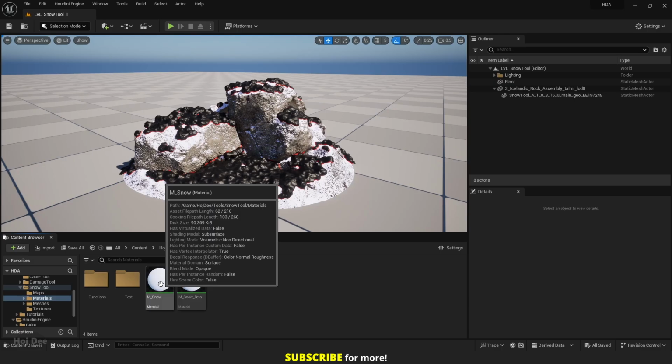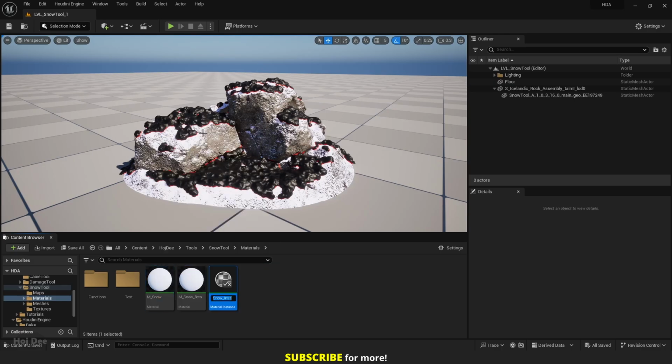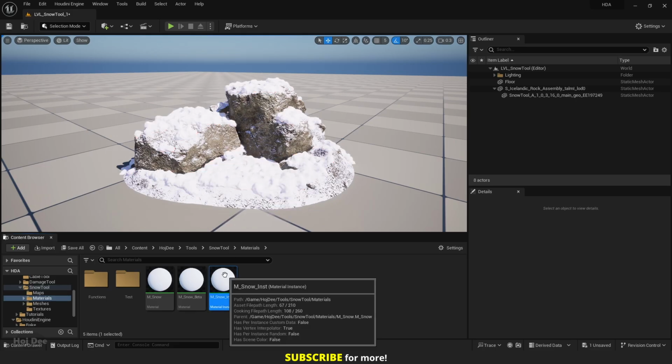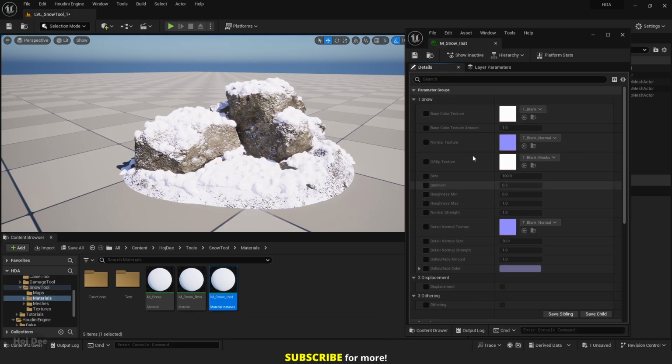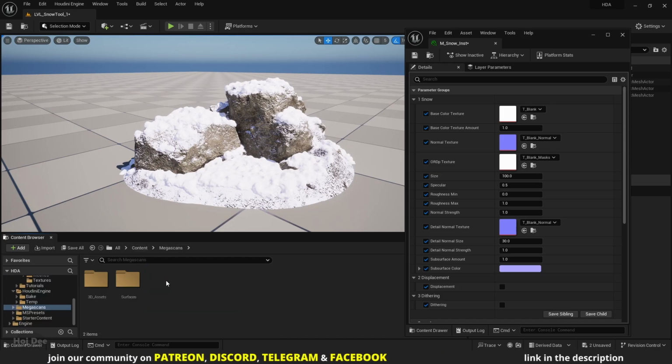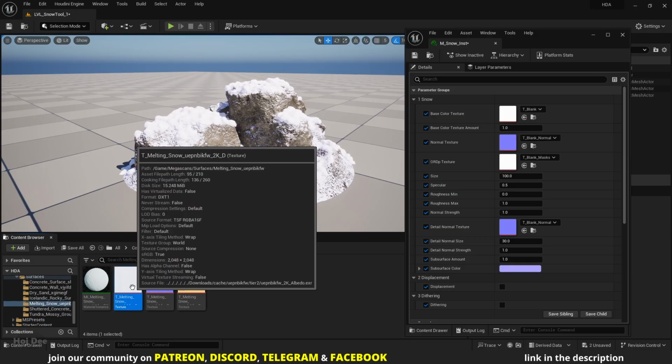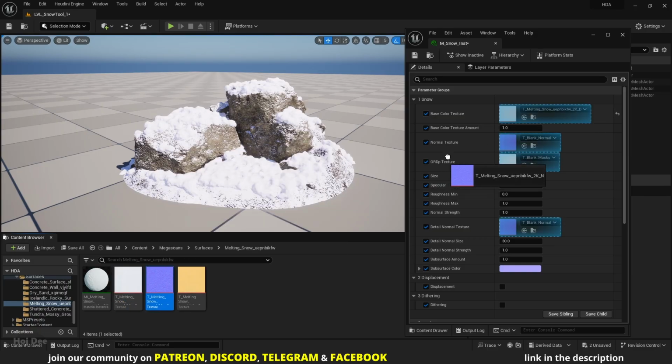So right click on the material and create a material instance. Save it, assign it to the snow mesh and open it. Let's enable all the parameters. First we should assign the textures. I'm gonna use the snow textures that we used for the material function. So let's go to Content, Megascans, Surfaces, Melting Snow and assign the textures. Base color, normal and ORDP.